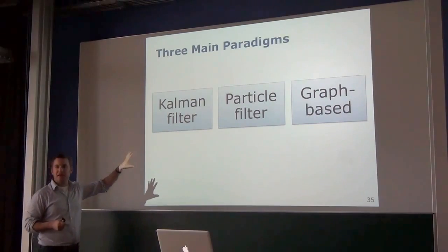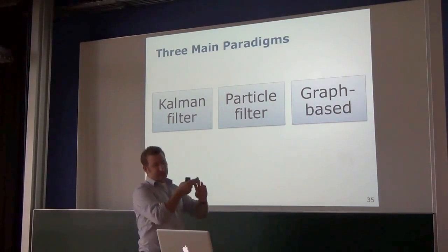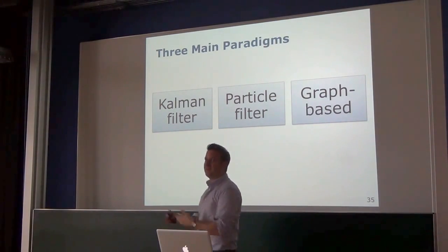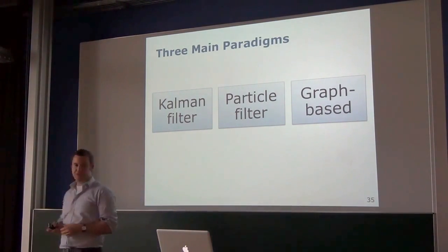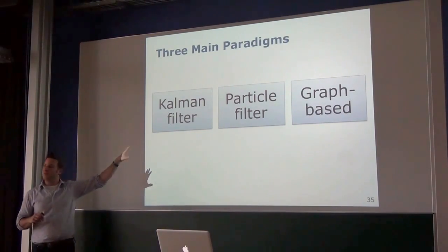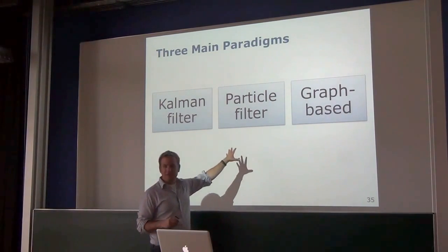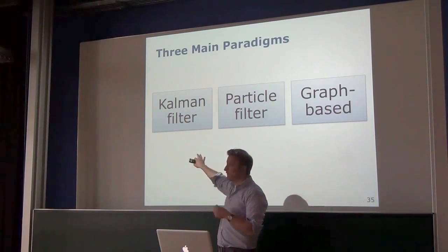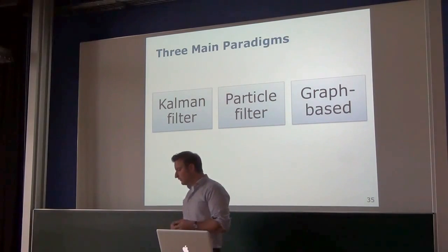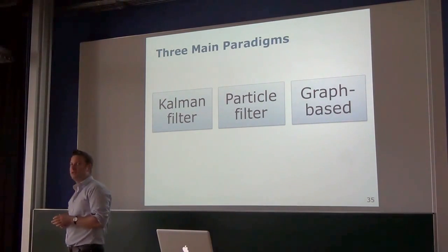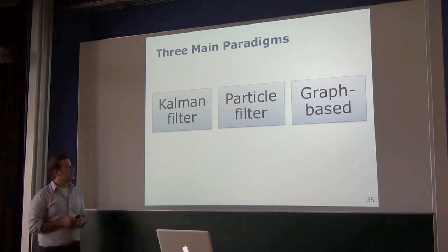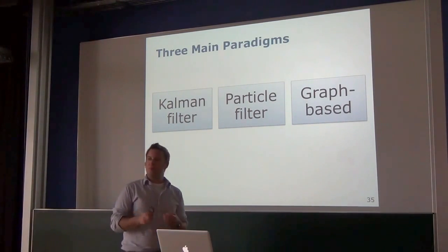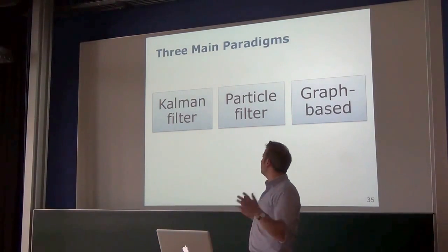The first one is the Kalman filter and all its friends: Kalman filter, extended Kalman filter, unscented Kalman filter, information filters, sparse extended information filters, this whole family of approaches which we also will discuss in the course. It's the approach that was started with. Then as an alternative, particle filters have been proposed. A particle filter doesn't assume this Gaussian distribution anymore, as the Kalman filter does, and has a sample-based representation, a non-parametric approach to estimate where the robot can be and its uncertainty. This is computationally more costly, but gives us more flexibility, but also has its limitations.